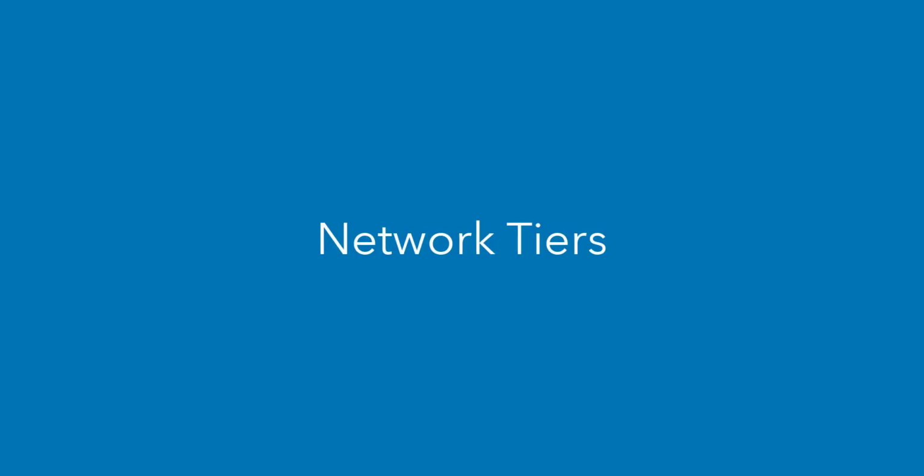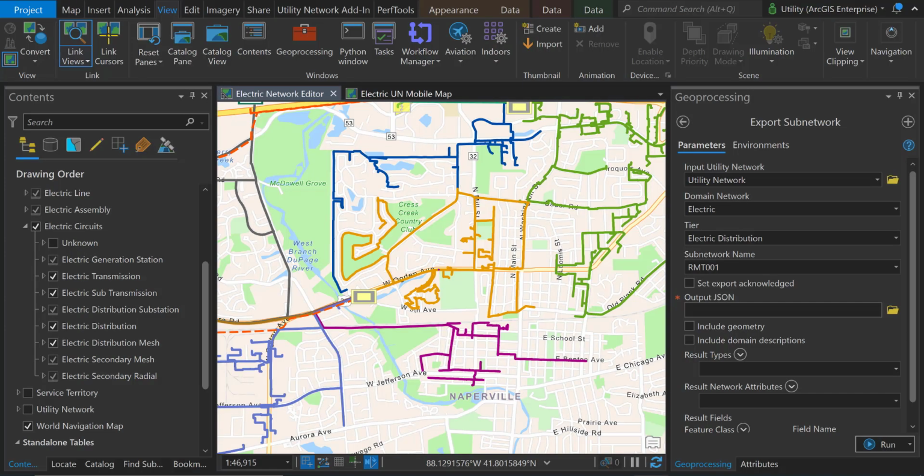Next, we'll talk about network tiers. One of the advantages of the utility network is that we're now able to trace and monitor our electric network between both distribution, transmission, and generation in the same map using tiers. So these tiers are used to organize a natural hierarchy in a domain network. In electric, they typically represent voltage or characteristics of the network.